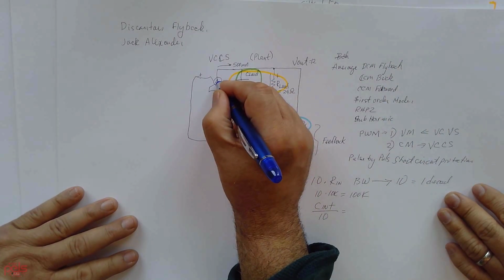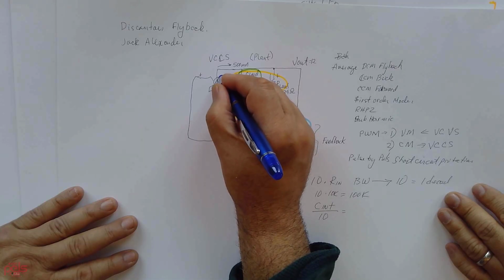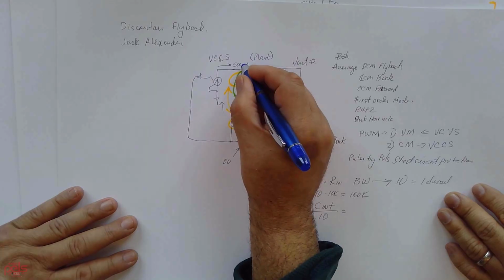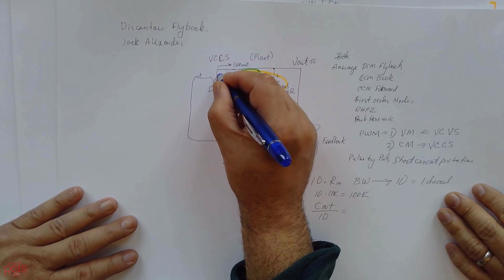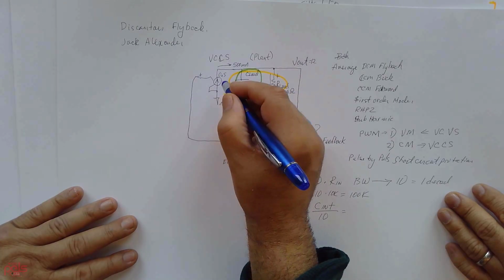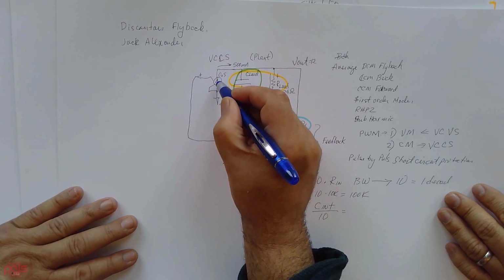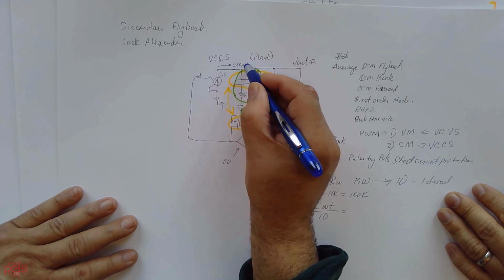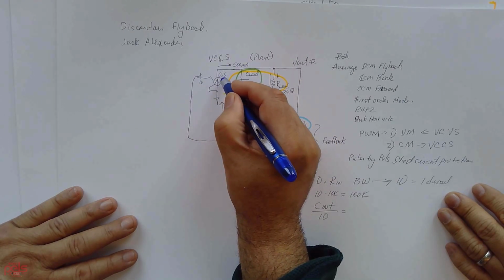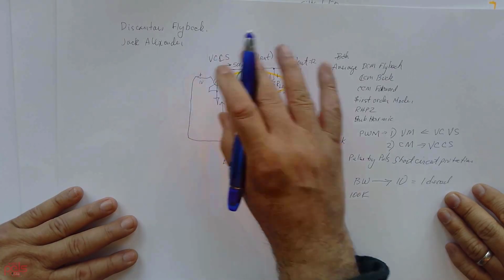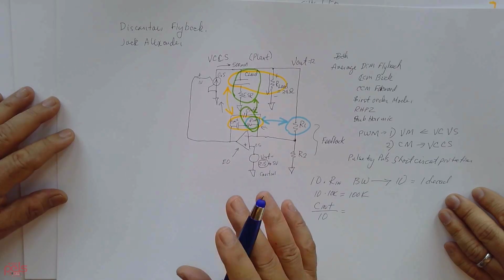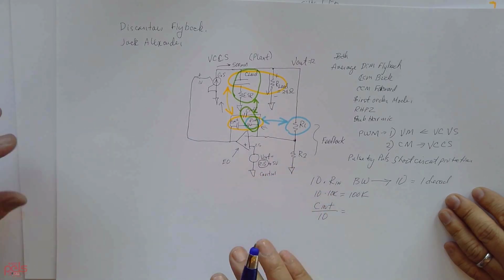In Spice, when you double click on the source, it'll ask you for the gain. So if you want 500 milliamps here, you would set it at 0.5 or put 500 m. Whatever current you want to flow out, if this is one, then you set the gain to your current, and that will ensure that it's biased correctly. It will converge, and you'll get a beautiful block.